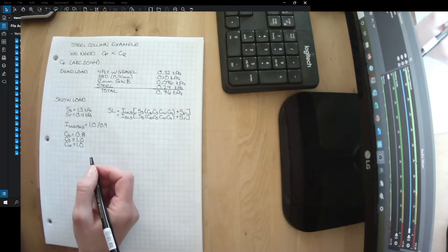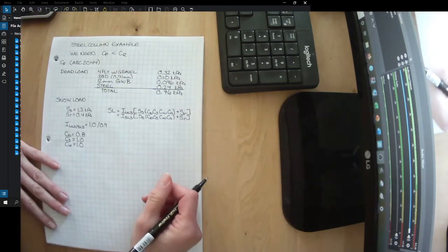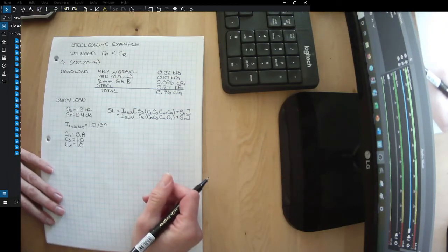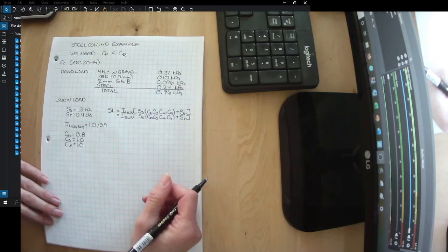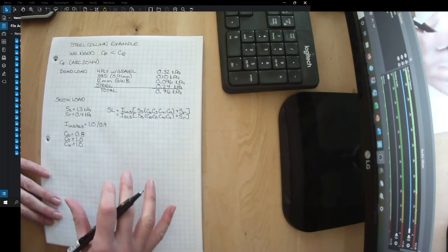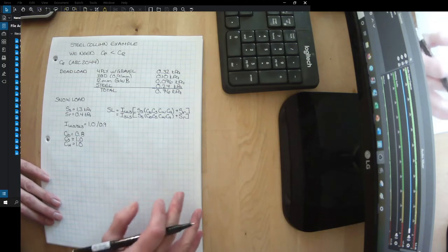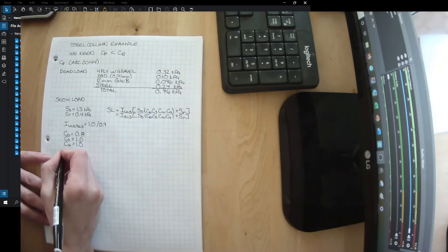So this is saying that if it's out in the open, the wind can blow the snow off, but you have to have nothing taller than it for a kilometer away from it, which is almost impossible in our zone here. Certainly in Brampton. Maybe in the prairies, you could get that. And then north of the tree line, they have another equation for it as well.